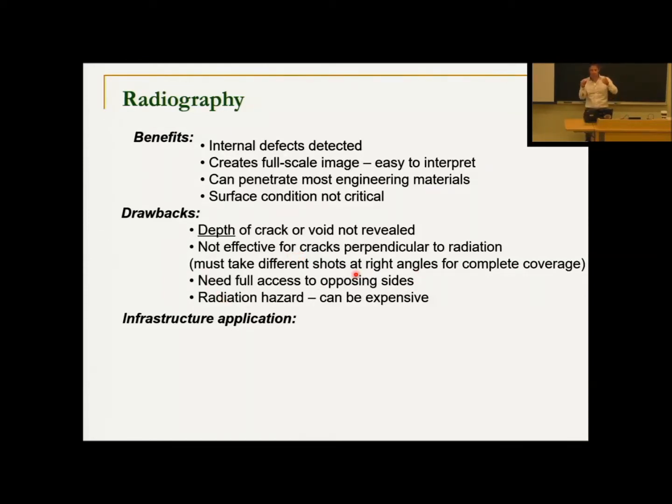The one huge problem is that you need access to the back side. It's not a one-sided method. Source on one side, detector on the other, measuring the penetration. And then finally, it's a radiation hazard. And because of that, that adds risk, it adds licensing requirements and other kinds of hazards. But still, it has its application.